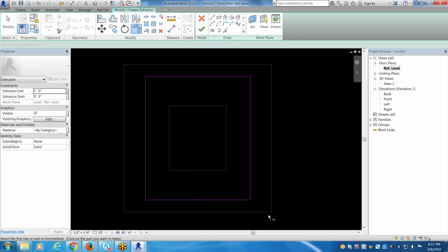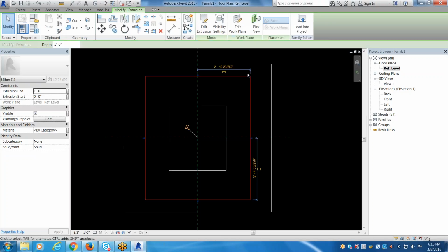So you can see there was no moving to a line. We know the midpoints are perfect because we used the mirror command. So we used symmetry to help us here. Maybe just drawing a rectangle and moving it would have been faster, but this comes in handy a lot. So let's click Finish now that we have our plate.